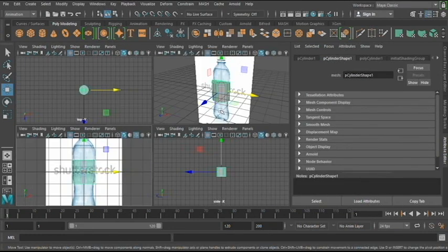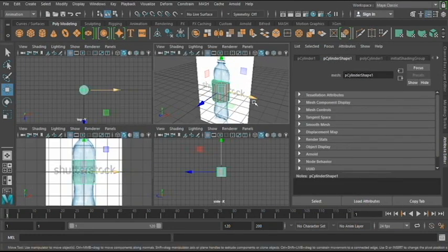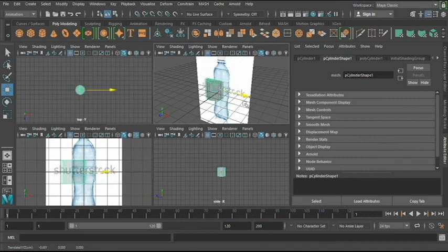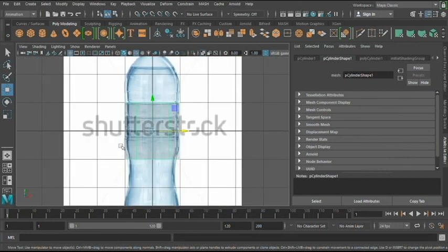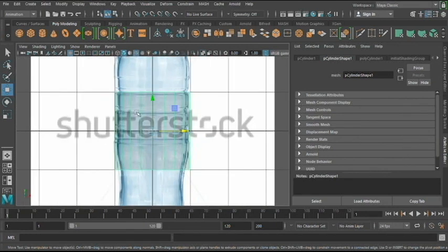You can see over here that as we move this object in all of the views, it actually changes. So we're going to hold right click. Holding right click is usually for specifically modifying and manipulating vertices or faces, or setting a new material.